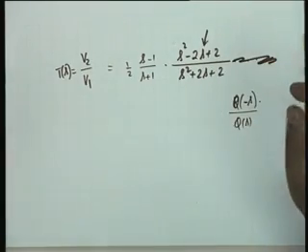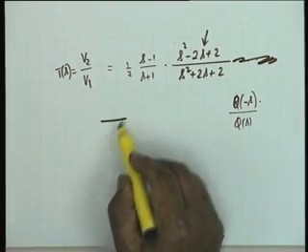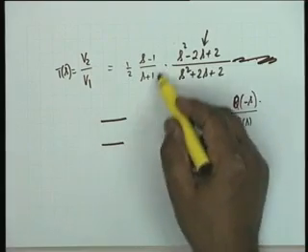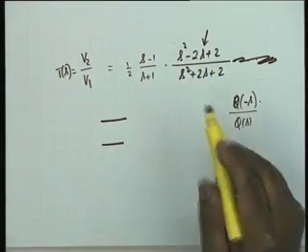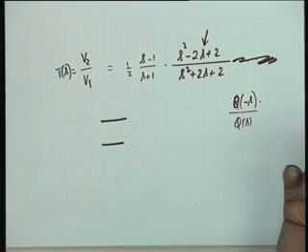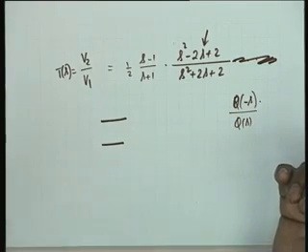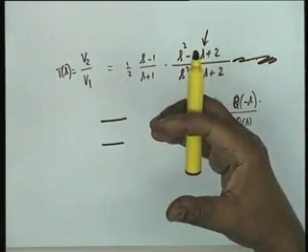Now obviously the realization would be very simple if we could realize these transfer functions individually and could multiply them. This is like achieving a gain of 1000. You can have an amplifier first stage of gain 100 and the next one 10, provided they do not load each other. That is, when the second stage is cascaded to the first, it does not load. In other words, it does not reduce the gain.